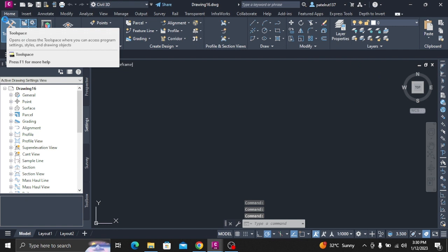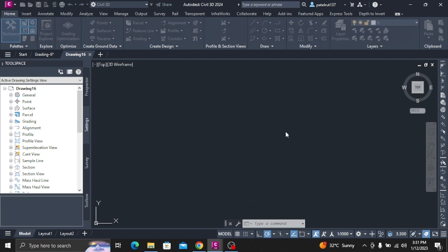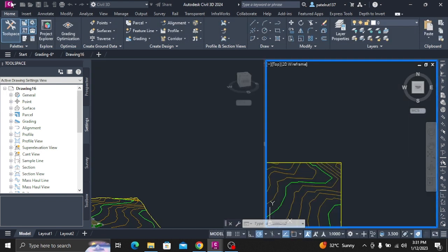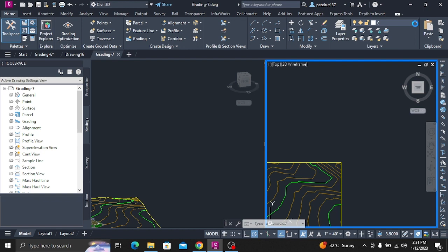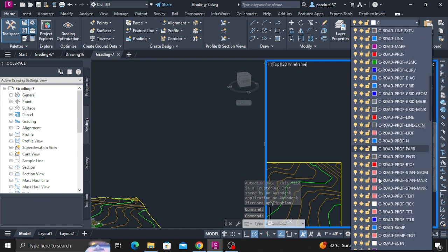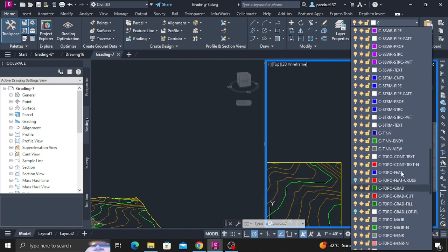Click Flatten Grade or Elevations. In the Flatten dialog box, select Constant Grade. Click OK. Notice that in the Grading Elevation Editor, the grade ahead and grade back values are updated to a consistent value. When you flatten a feature line, the points between the start elevation and the end elevation are set to the same grade, effectively eliminating the grade breaks.